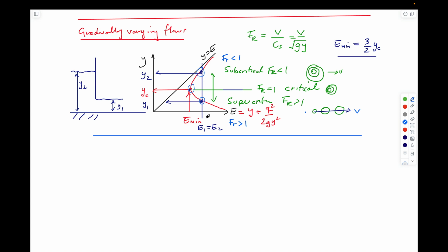And so if you are given, for instance, a volumetric flow rate, this curve here would be for a specific value of Q, defined in this expression here, and all the terms on this are flowing at that same volumetric flow rate per unit width of the section, but at different depths. So this would be flowing at a deep depth but slowly, and this would be flowing at a shallow depth but much faster, so that the volumetric flow within the section is identical on these 2 points.